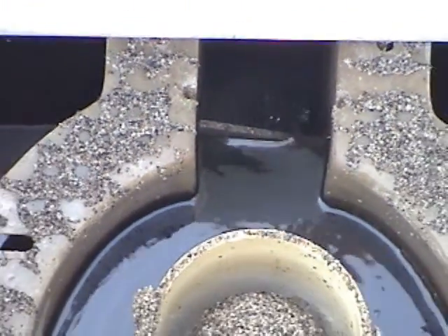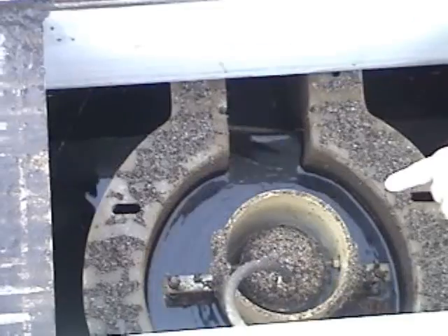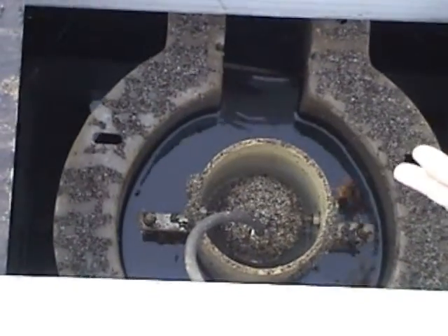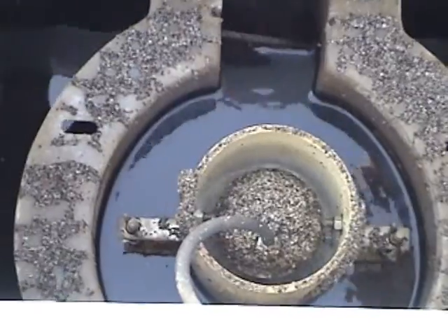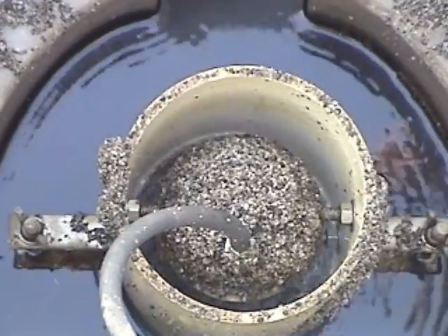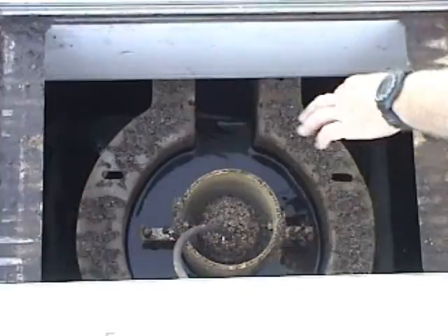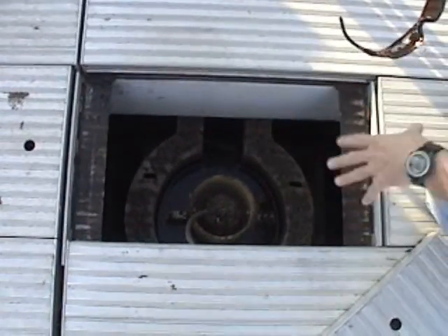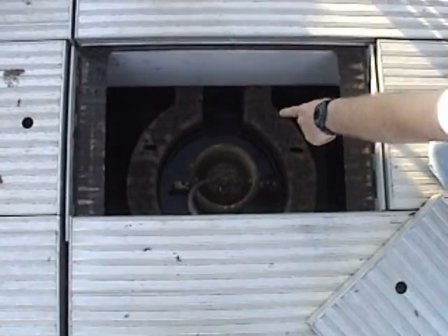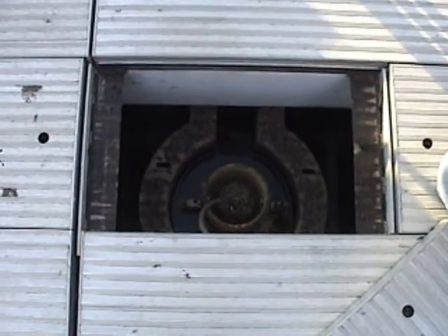As the water passes through the sand media, dirt becomes trapped on the sand. To backwash it, you have an airlift pump right in the center of this, and the airlift pump is pulling the sand up through the center of this pipe and agitating it. The air bubbles are shaking the organics loose from the sand, and then that dirty water floats up here and flows over the weir, through a trough, and is returned to the head end of the plant. That's the backwash water.